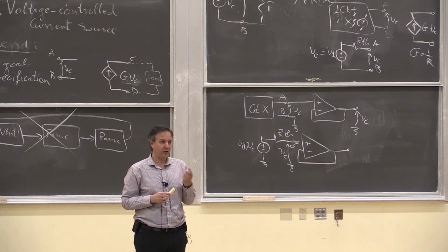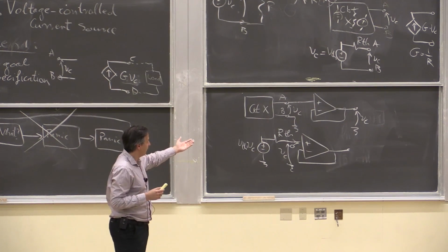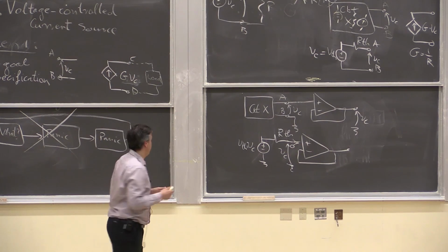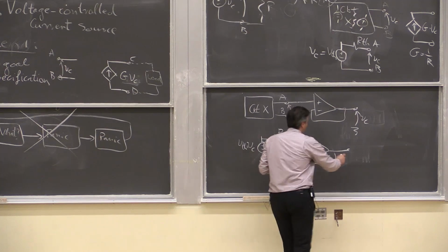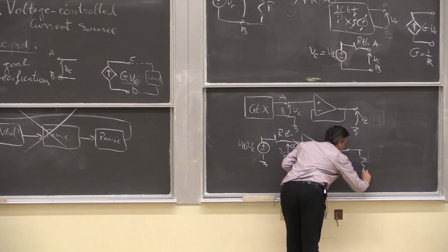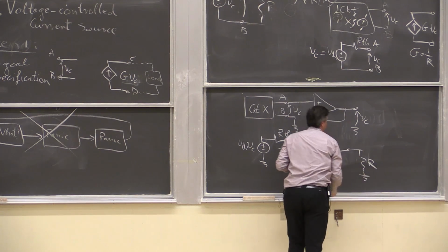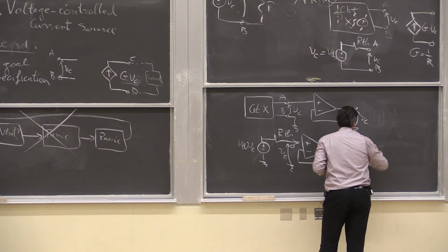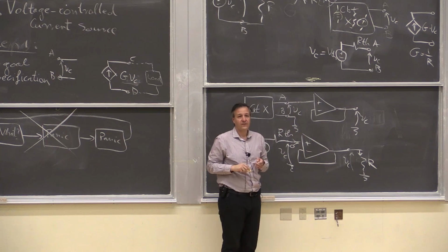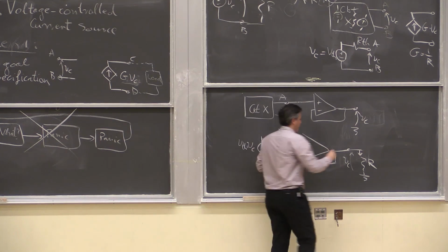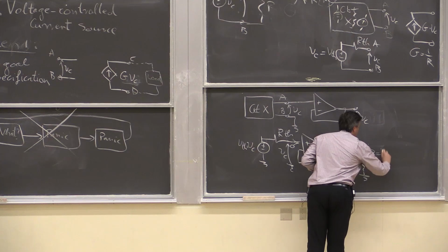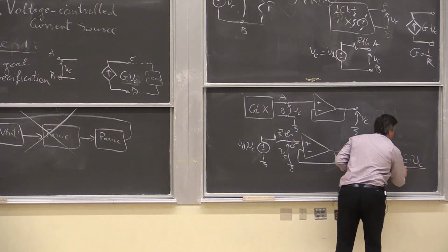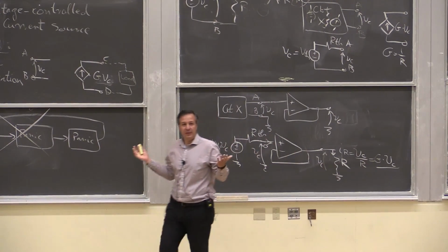Okay, you're getting somewhere. Let's first figure out how we turn voltage into current. You're saying, let's use a resistor. We're going to add the resistor R here. This was VC. So what is the current through this resistor? Yeah, so this IR will be equal to VC over R, or G times VC. Right? Am I done?